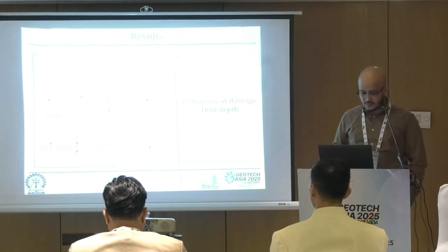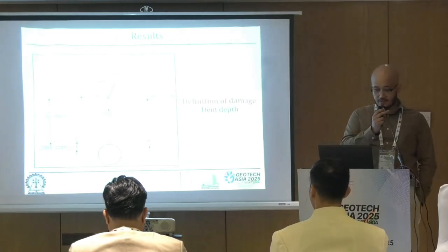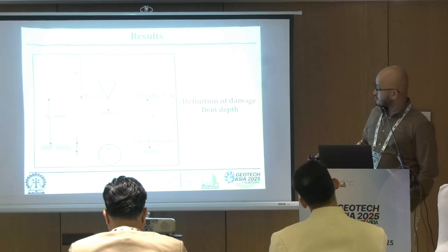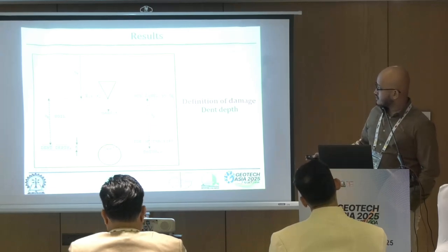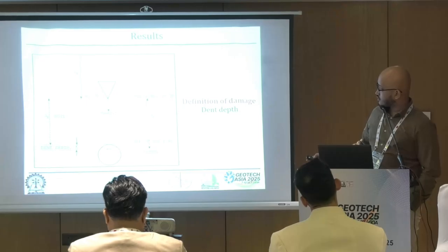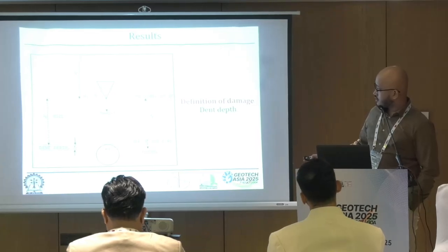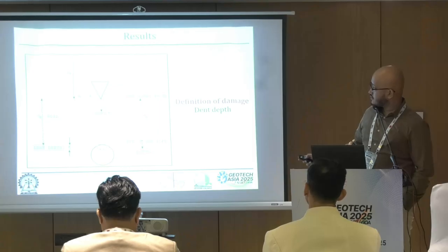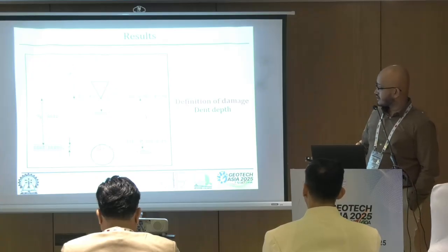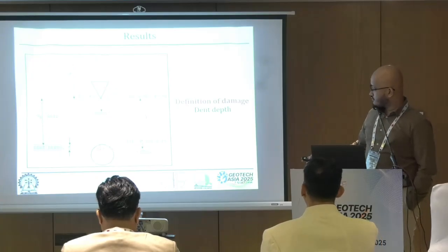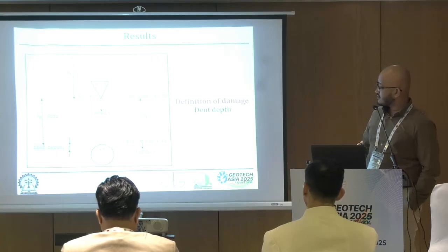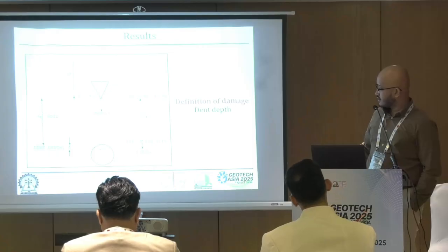Okay. Now, let me try to explain this whole process again. Generally, the height of the fall through water has been modeled with the help of an impact velocity. Obviously, when the object is at the point of contact with the soil, it brings a certain level of kinetic energy as well. As it moves through the soil, the velocity decreases as it decelerates, and eventually when it hits the pipe, it creates a local deformation at the pipeline itself.